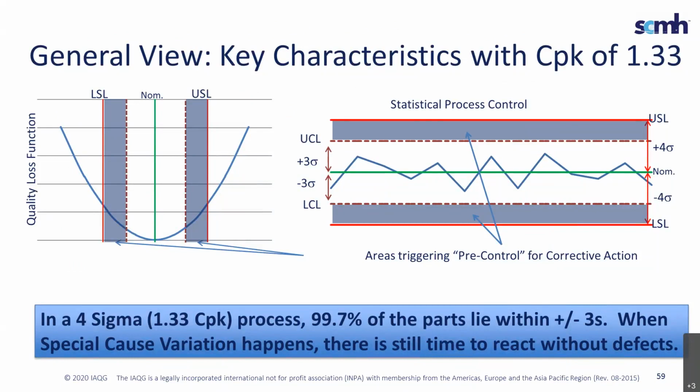In effect, if you want to calculate your Z, it is the number of standard deviations away you are from the closest spec limit, and then basically translate that into the number of parts defective. It's also the inverse, or 1 minus the area under a curve of a normal distribution. So it's the number of defective. That's the Z table. Okay.